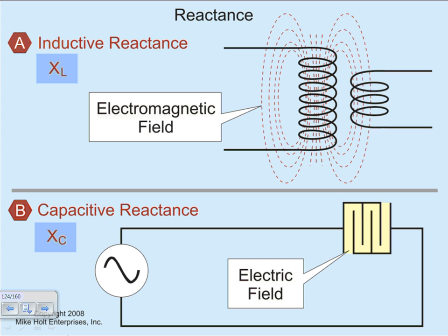So what do I need to do with the necessary evil? Not get rid of it, but neutralize it. I use the word neutralize. You're really not getting rid of it; you are neutralizing it by minimizing its effect. So the XL, you neutralize by minimizing its effect by adding what? Capacitors. That's the whole power factor correction concept.